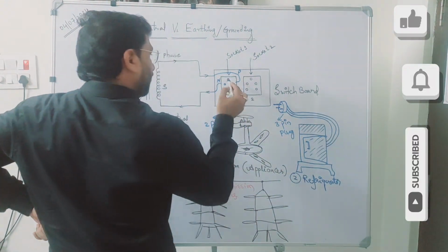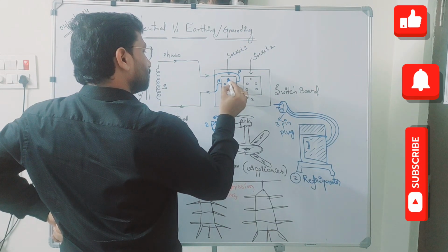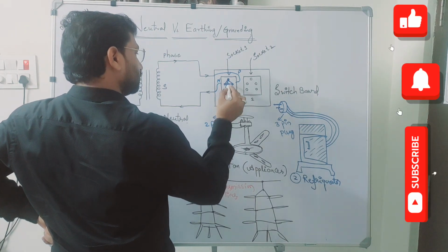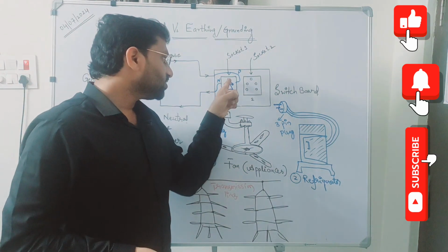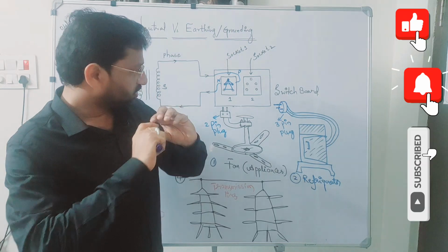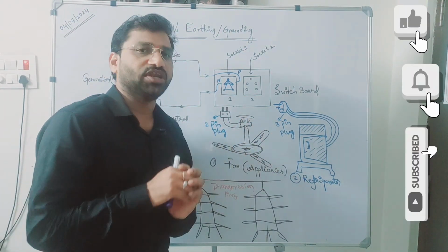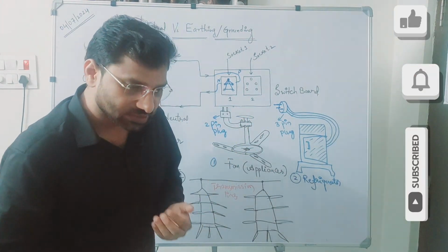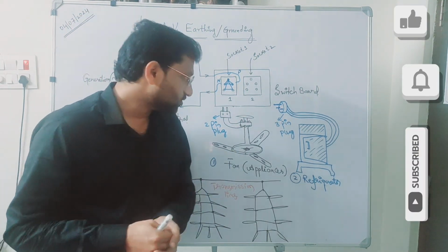Here, in this switchboard, this is one connection, and this is another connection. As I told you, since we have two types of connections, you can use either a smaller plug or a bigger plug depending upon the current capacity. You can use 16 amperes or you can use 10 amperes. Think that this socket is designed in such a way that it is going to accept 5 amperes, 10 amperes and 16 amperes, of course even 12 amperes also.